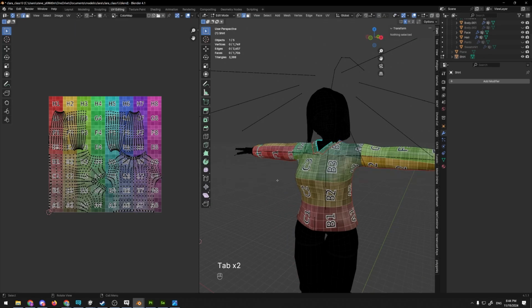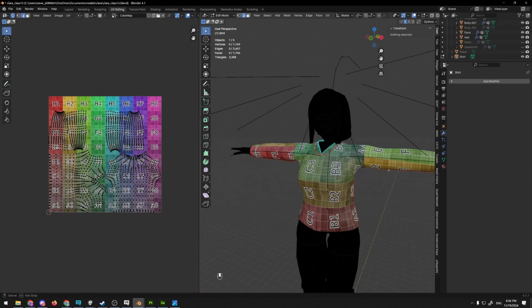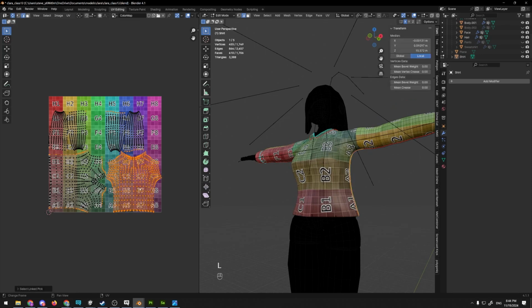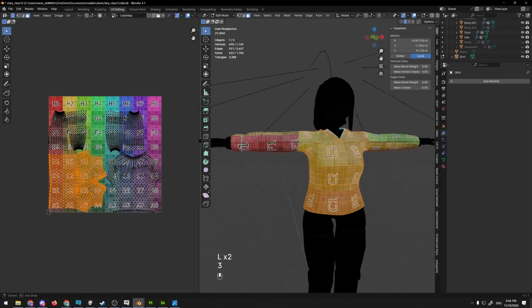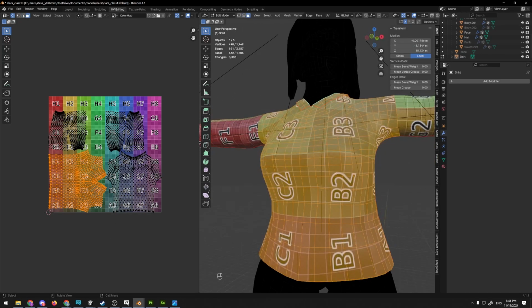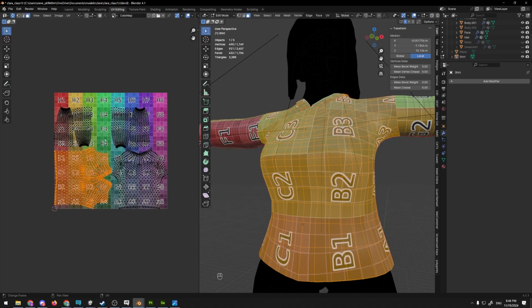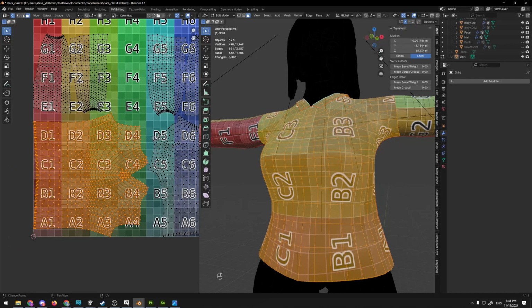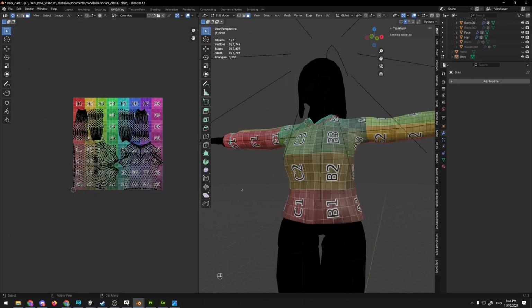Notably, a lot of times you're going to want an image, like on a t-shirt, you might want a graphic tee. It can be good not to put seams in places where you want a contiguous texture, especially with one with a lot of detail. So I left the entire front of the shirt as one UV island, which is this whole section right here. That way, if I ever want to apply an image onto this part of the shirt, I can just slap it basically right there and it would just work, which I can show off later in Substance Painter.